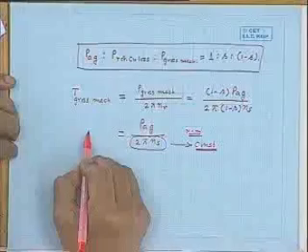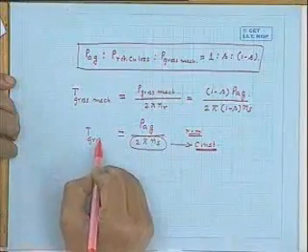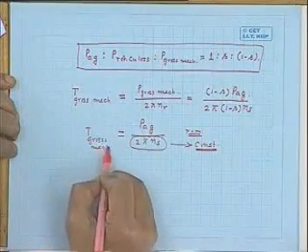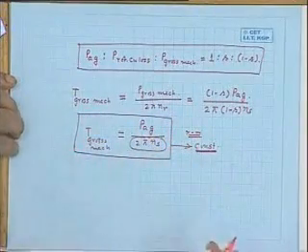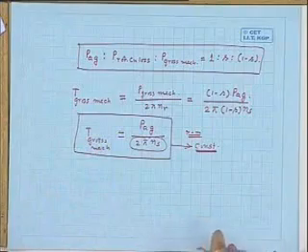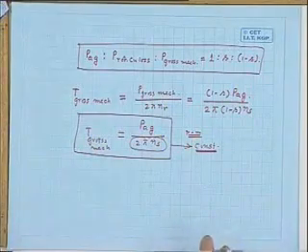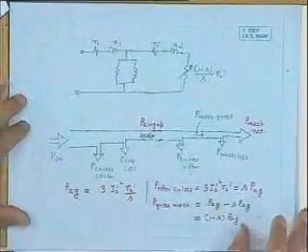With this in mind, that actual torque in Newton meter will be this 1000 divided by 2 pi NS. So sometimes torque is also used in watt, and that is called synchronous watt. So these are very useful formulas, you should remember. Okay,